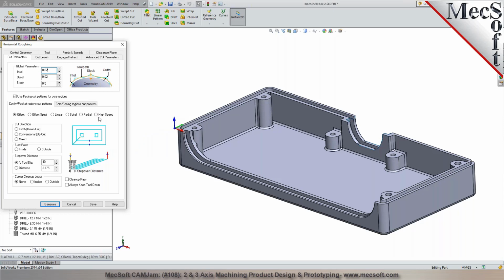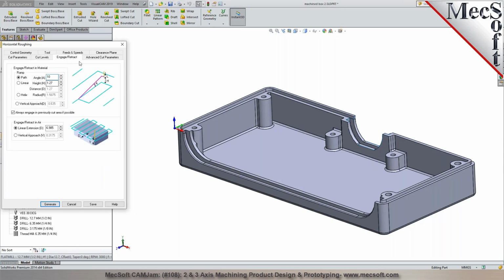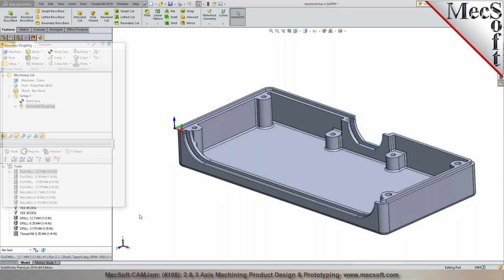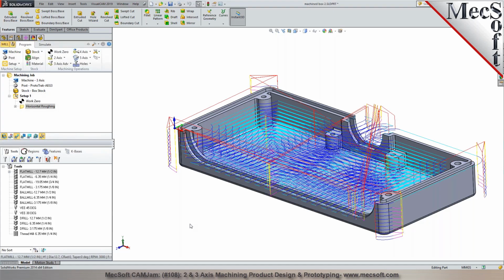Okay. Yeah. So you can program this using a 3-axis roughing operation in here, and I can specify all these cutting conditions that you're looking at right there, and then pick generate. So in this particular process, it's going to look at the part and the stock, and automatically compute the toolpaths. Any questions while the toolpath is being generated? No.